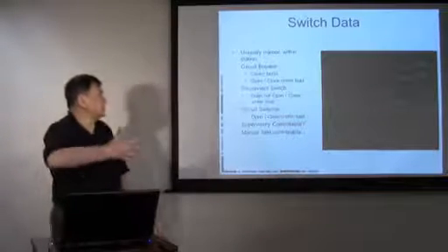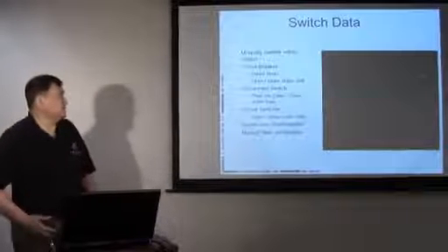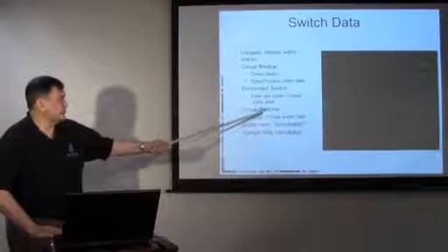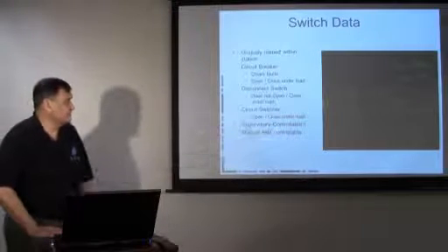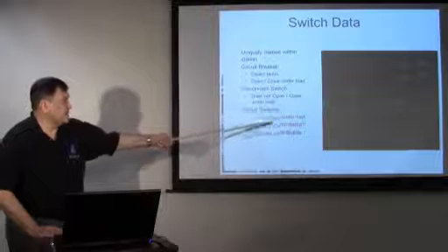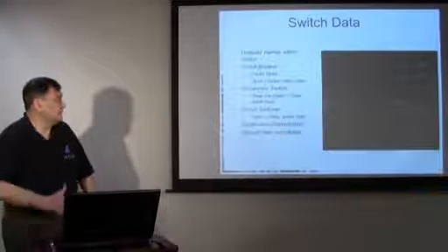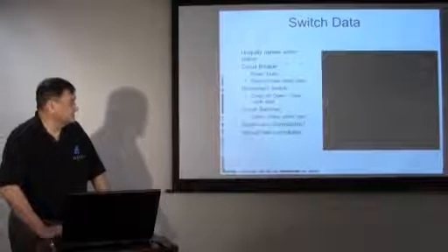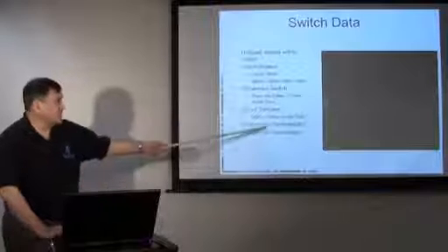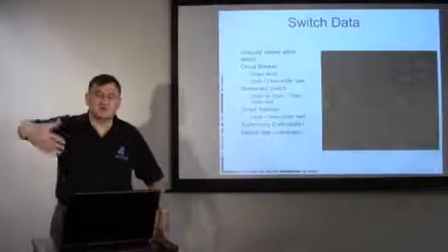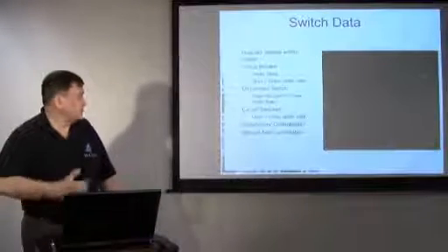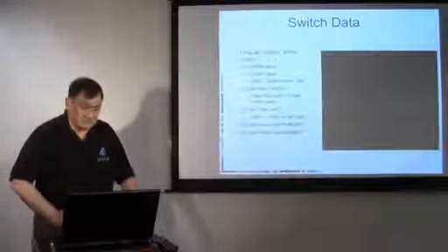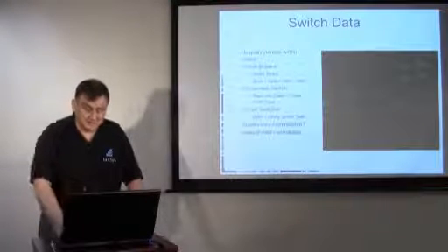They cannot open and close under load, and they cannot clear faults. We can also have circuit switches which can open and close under load, but they do not clear faults. And then it's important to know, can the operator control that under supervisory control manually, or does he have to send out an operator to walk up to the switch and crank it open?